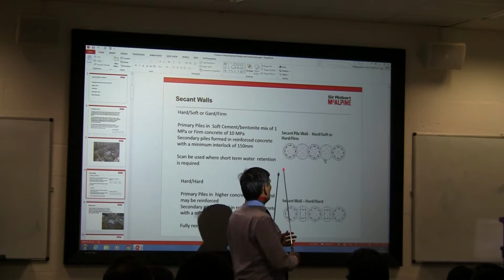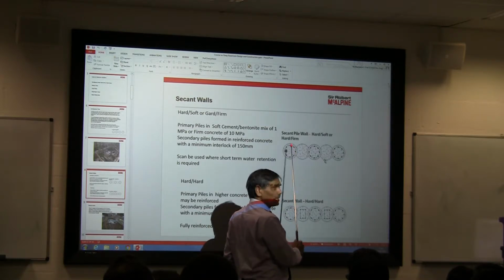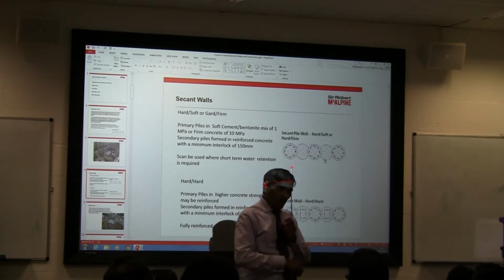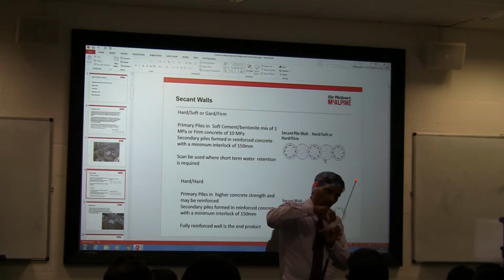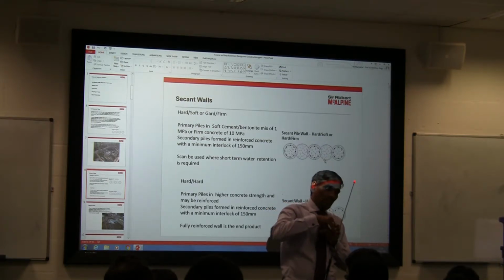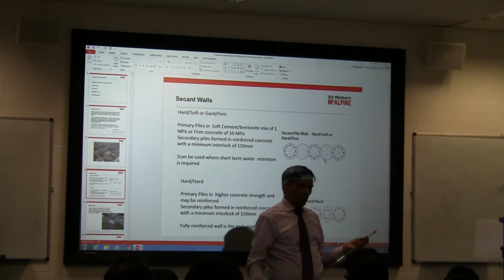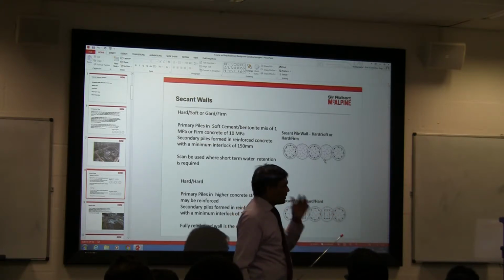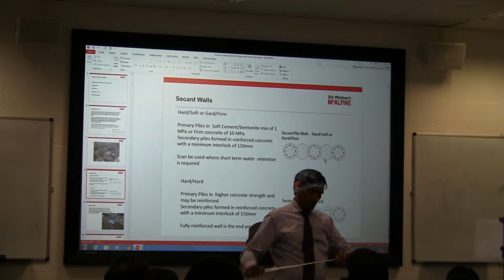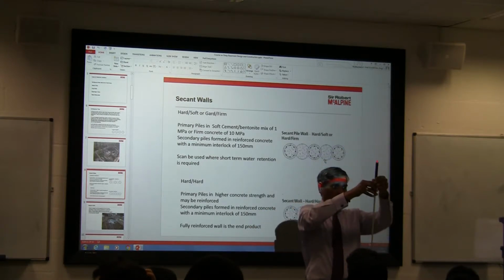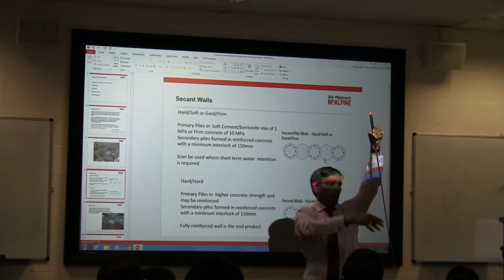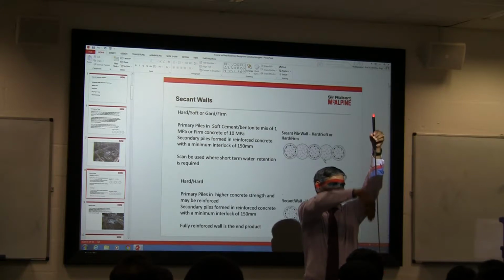The reason is, we want to make sure there is enough interlock between the concrete itself, the auger itself when it is cutting. We want to make sure there is going to be enough cutting through the concrete. It's very unlikely that you will find that as long as you maintain the verticality of this, how it is actually going, and then the other one comes there. If it is tilted like that, then there is no interlock with the other pile, so you got a gap.